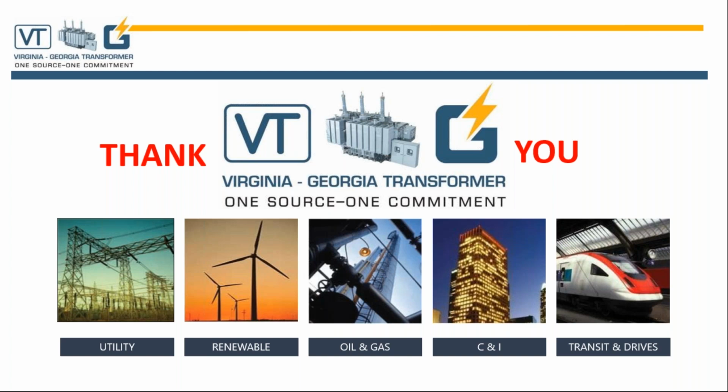So it is either delta or Y; irrespective of that, the voltage increase will determine how it impacts the transformer. So basically, Bala, what you're saying is, regardless if it's delta-Y or delta-delta, YY, the effect is really related to the increase in the excitation in the core. Yes, and there will be some difference when it comes to the impedance for the zero sequence, which is third harmonic. That will play a role, but that will change based on delta and Y, and that again depends on how the transformer is designed. For example, if you take a delta-connected inner winding, your zero sequence reactance is lesser than positive sequence, and if the delta is outside, it is different. They are not the same. They are not reciprocal as in the case of a positive sequence.